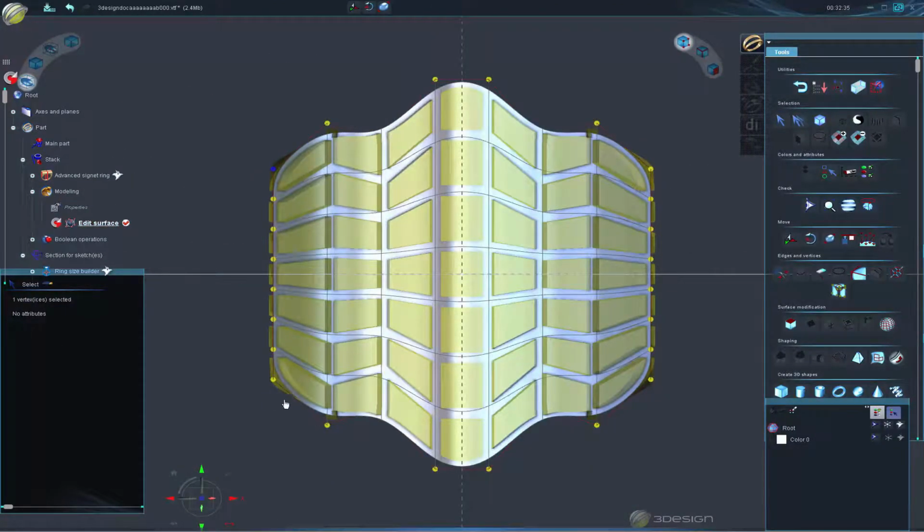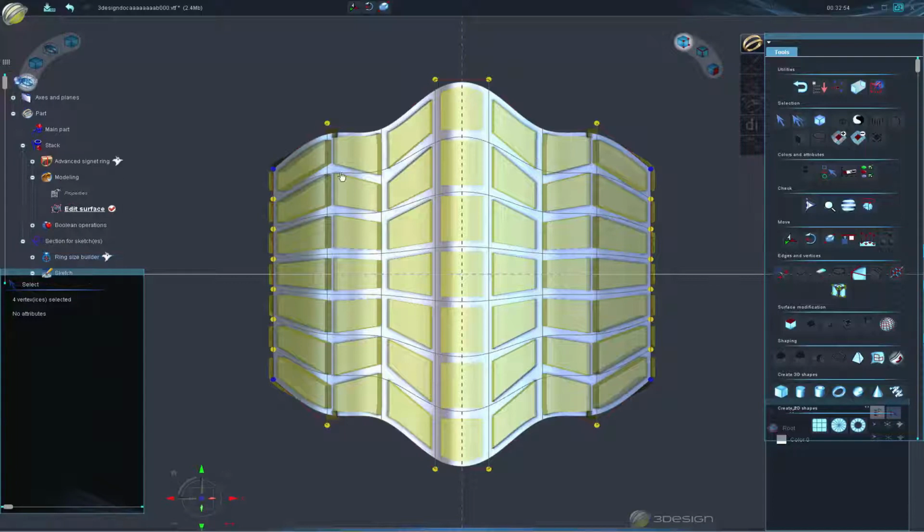Okay, you can select these points, and the only new tool which was created for this very purpose is in your edges and vertices section. You have a transform a vertex into a point, so that will create an actual point there instead of a normal vertex, sharpening your edges. So if we recalculate that, we will see those corners become points now. Sometimes your mesh shape will have, like I said, when you Boolean it together, you're going to have some weird results, parts of your model.